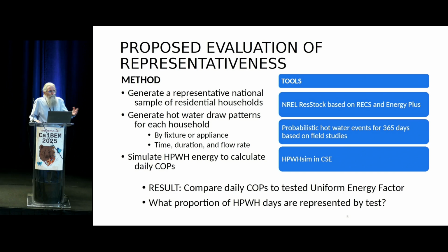Run it, put virtual people in all those virtual houses, have them use virtual water heaters and virtual hot water, and see if the efficiency of different water heaters, different models like an A.O. Smith, a Rheem, different size tanks in different locations in the house, if the average of that gives you a number that's reasonably close to the UEF and is in the same order, so water heater A is always better than water heater B.